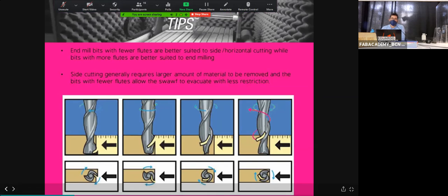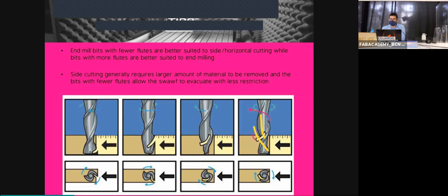When we cut, we are basically taking material out. We are rotating at really high speed. We are cutting a little piece of material and we are pushing it out. For example, this end mill is an up cutter. It's pushing the material up. So it's a generalistic end mill. Some end mills, what they do is rotate, the blades are in the opposite direction, and they push the material down. You will say, you push the material down, there is no way to escape. Yes, on the back of the cut.